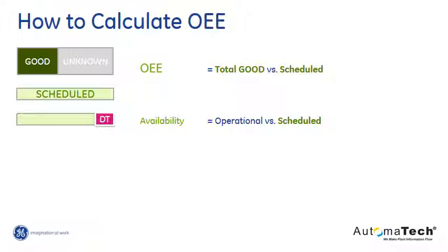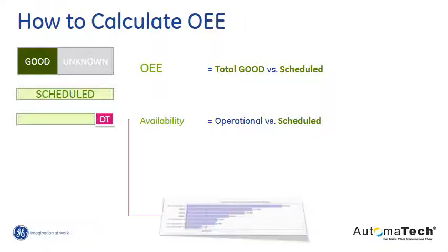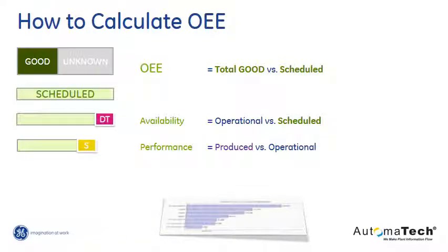And some people do this already with clipboards. Let's start obtaining this information. Let's let the machine tell us the reason why it went down, and the exact duration for those different reasons. So that ratio between the total scheduled time and the smaller green bar there is essentially your availability. Any time that you didn't spend running is that downtime. And we want not just that, but we also want the ability to drill in and see the different reasons for that time period, why we weren't running, motor failures and things of that sort.